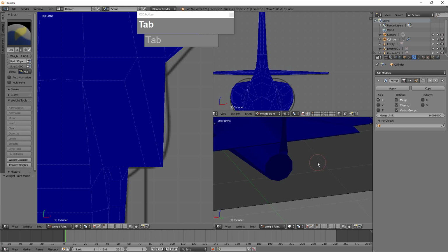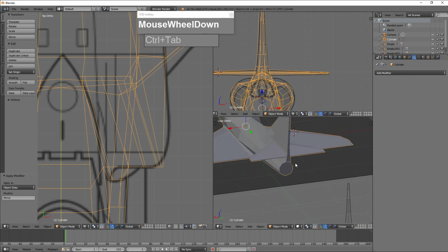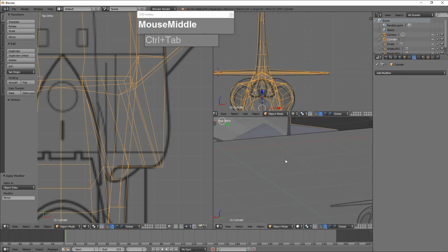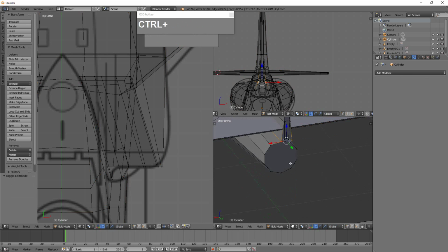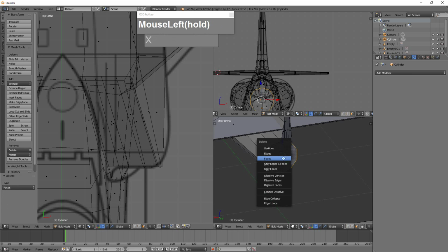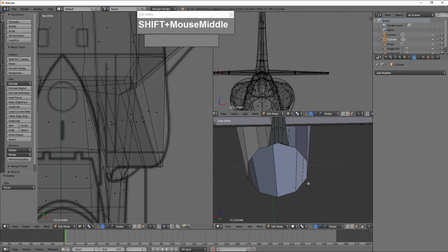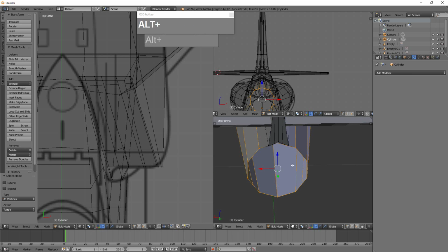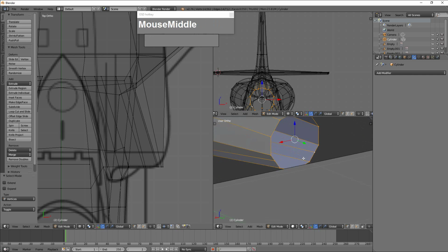Right, and then I'm going to go to edit mode. I'm going to select this central face here and delete it, this face as well. So right now there's an open hole here. If I go to vertex mode and Alt right mouse click, this circular nozzle will be selected, and if I want this to be perfectly round, I can press